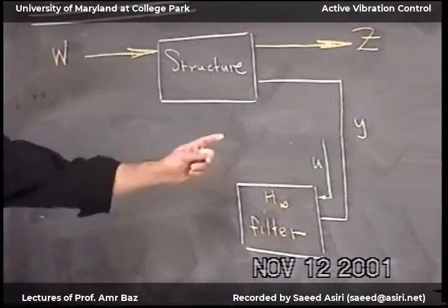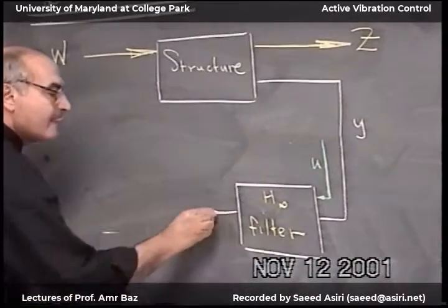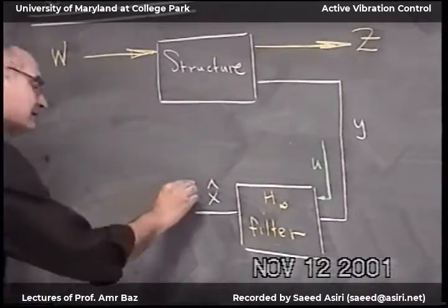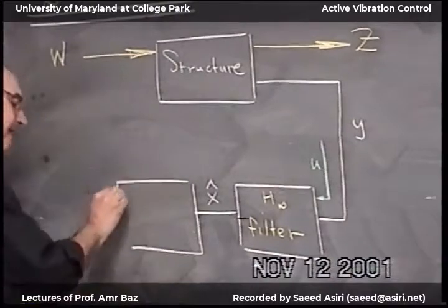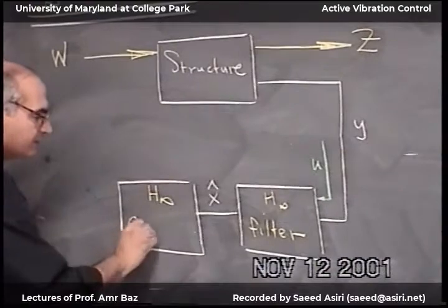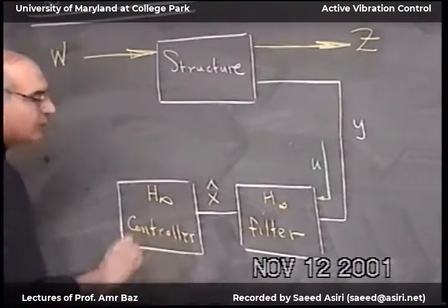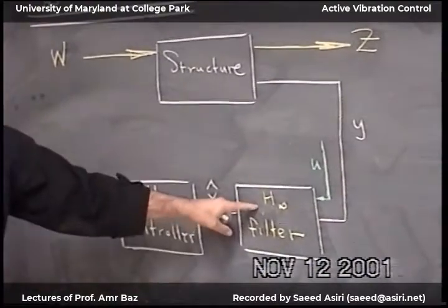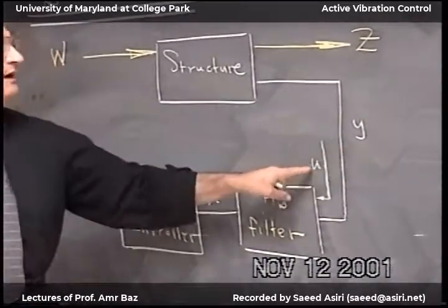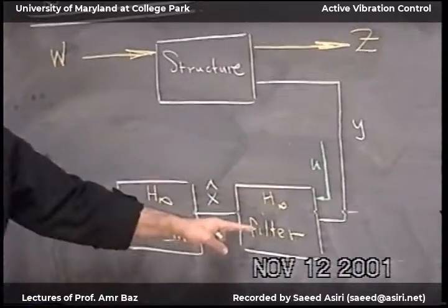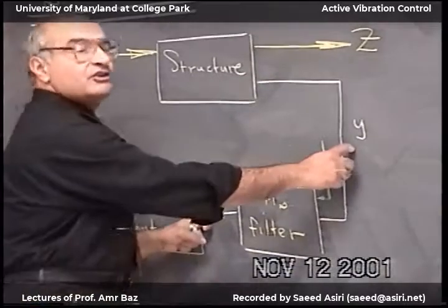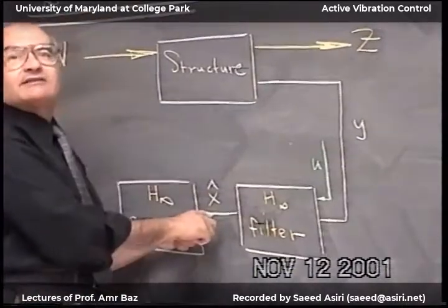Now I have these two, then I get from here X hat. I get X hat, I go into the H infinity controller. This block, we have all the details from the LQG. So I have the Y and the U. From these I combine with the L0, get the estimate of the states. Only measuring a small subset generates the entire state vector.